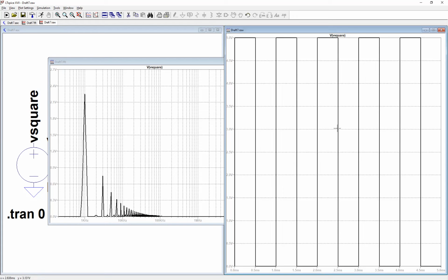So this spectrum I'm plotting is just the spectrum of 5 periods of a square wave. That's it. If you want a spectrum that looks more like an ideal spectrum of a square wave, I need to increase the number of periods that I see here. Then the signal approaches an ideal square wave, okay? But we will never be able to plot an ideal square wave because we cannot plot a signal which oscillates for infinite time, right? But we can approach it.